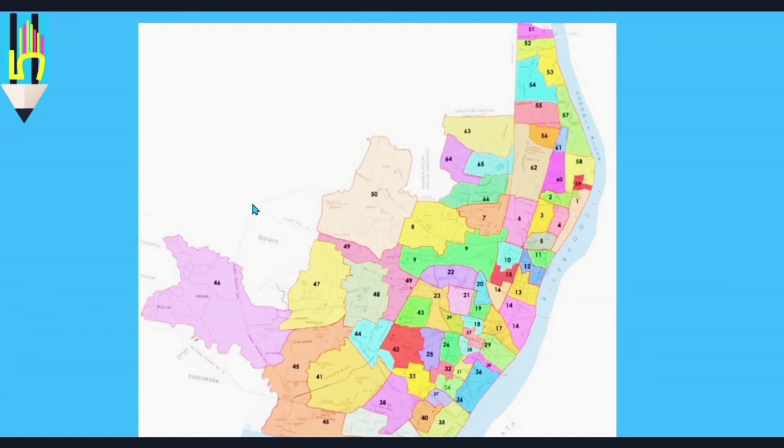So when we go to these places to collect data, we should always get this data, where there should be a graph containing the outermost boundary along with the ward boundary. Now the problem is most of the offices here give you hard copy. Okay, they will have the maps, but they will give them to you in paper format, and that becomes a headache because we have to work in WaterGEMS. And in WaterGEMS, if we are getting a hard copy of these things, we cannot use it properly in the background of WaterGEMS, because we can obviously build networks on this, but if we want to get the elevation, the XYZ coordinates, then that will become a problem.